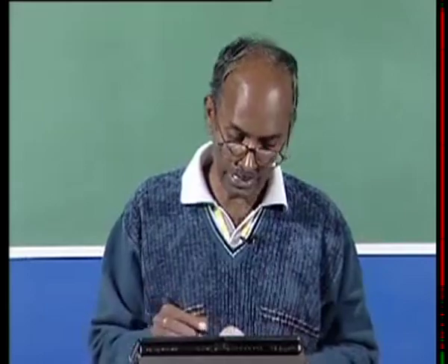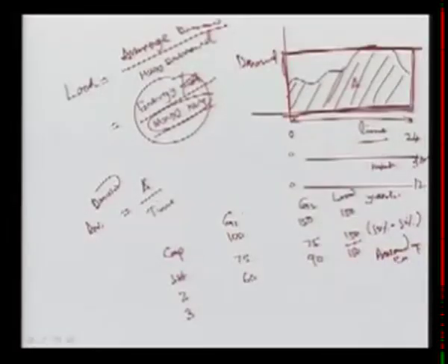Another case: suppose the efficiency of this is 35% and the efficiency of this power plant is 40%. So we can load according to the efficiency. Again our objective is to meet the load demand of 150, and if we go by efficiency, we have to load 70 here and 80 here, and again we are meeting the load. More efficient, more loading; less efficient, less loading. Various other combinations are now possible. Here I can say 71, why not 79, and so on and so forth.